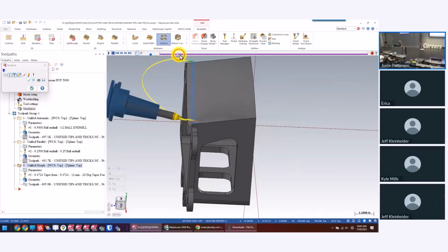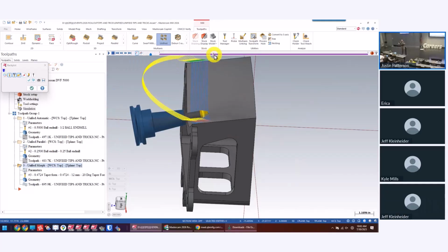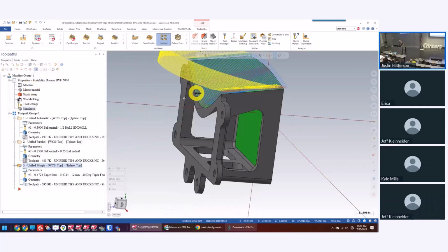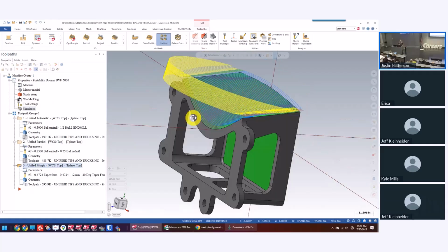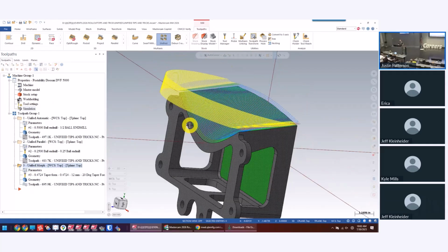Okay? I mean, that's pretty much the tool path in a nutshell, but I want to show you the next step that can clean these things up and make really nice looking tool paths. That motion's not the end of the world, but it's not super clean. A lot of machines aren't real good at doing multi-axis motions and rapids, right? They're not a fan of that. So watch what we can do just using our linking parameters here.